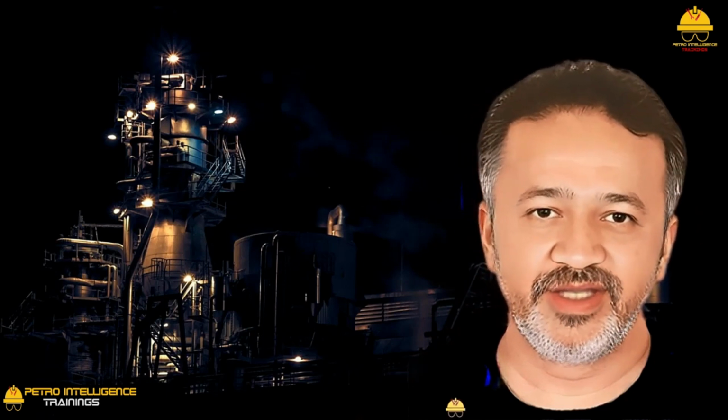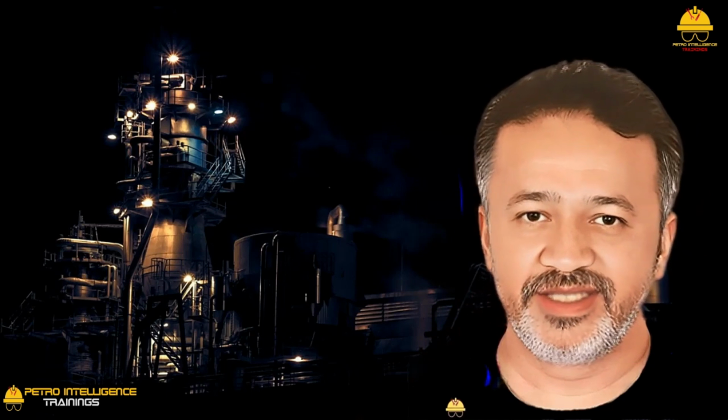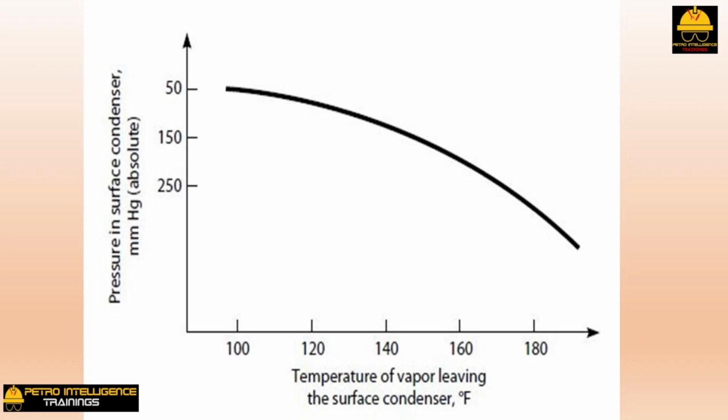Surface condenser problems. These include undersized surface condenser area, waterside fouling, lack of water flow, condensate backup, leaking seal strips around the air baffle, and excessive cooling water inlet temperature. To determine whether a poor vacuum in a surface condenser is due to such heat transfer problems, plot the surface